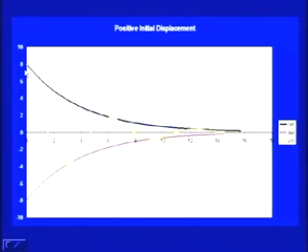You see, when we had over damping, we got motions which just go down. When we had critical damping, again the motions just went down. And here, the motion goes down and up and down and up and then dies down, that is, it stops. So, this is what is called under damping. So, we have discussed the 3 cases of this differential equation which governs the motion of a basic mechanical system, that is called the mass spring system.